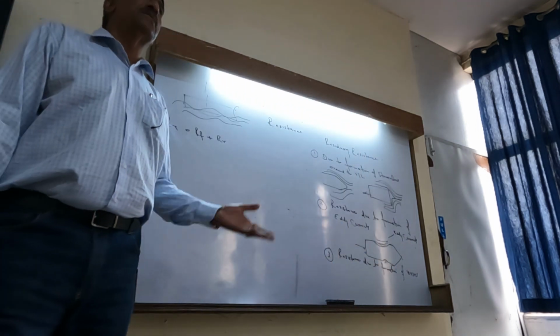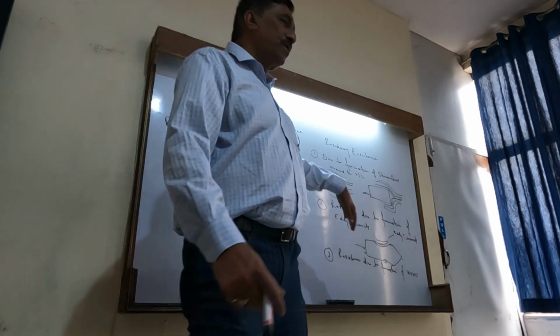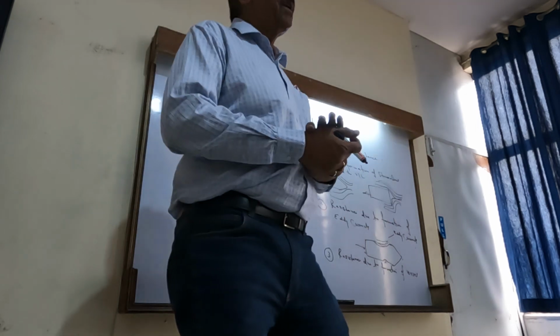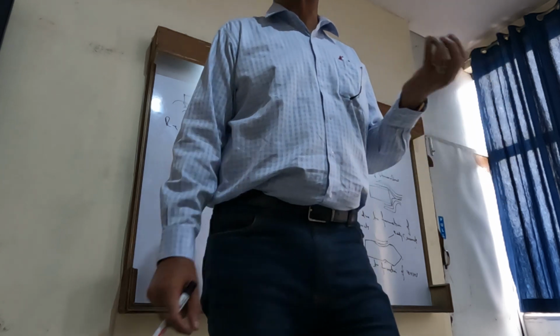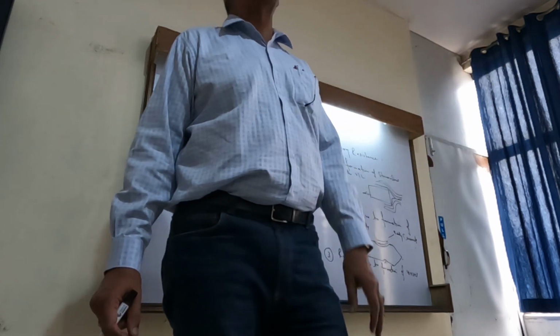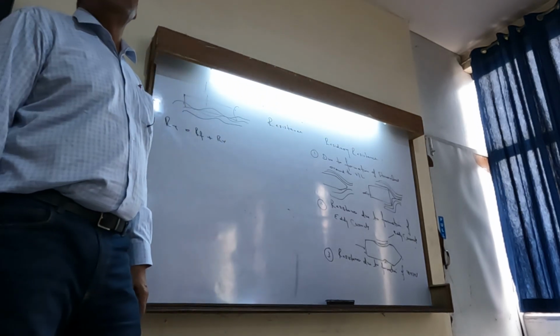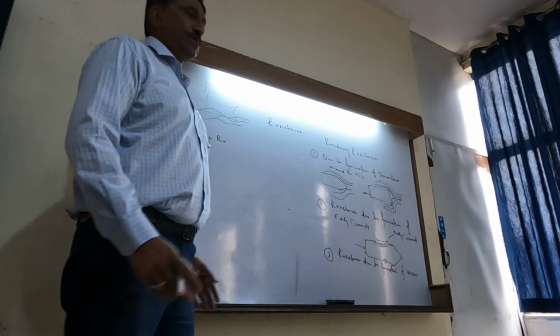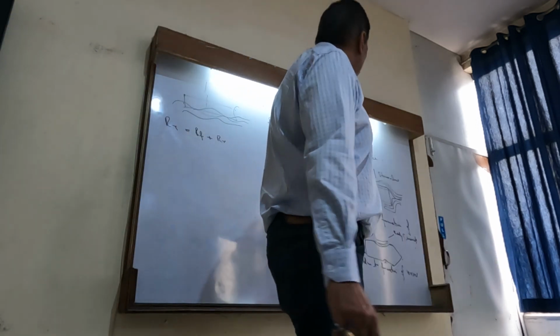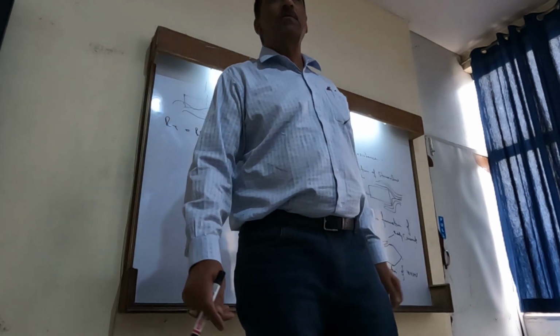Technically yes, but because of this knowledge only we are profiling in such a fashion that the residual resistance is as small as possible. Now since it is the sum of the two, you will find that for slow speed vessels, residual resistance may be only 5% of the total resistance.